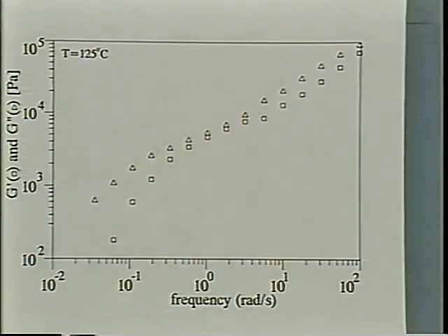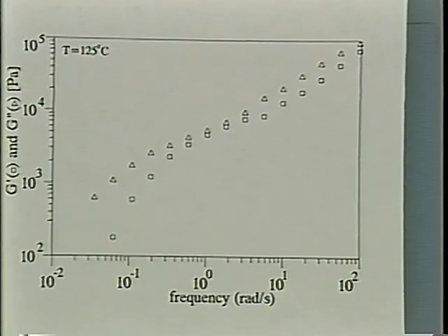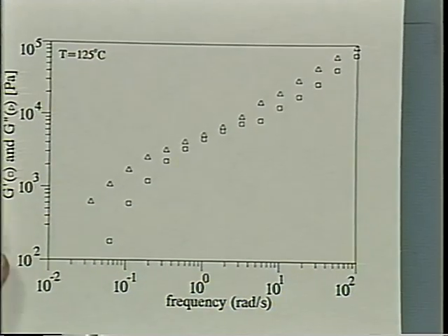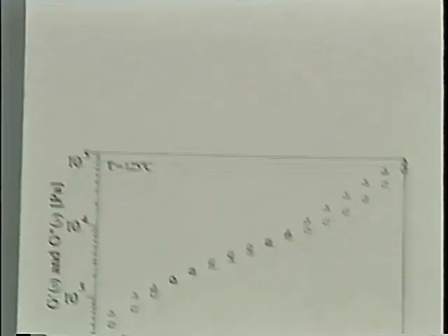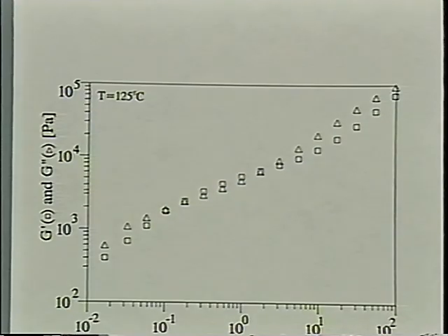And while the cylinders are healing, we are exposing the sample to large oscillatory shear. Just to show you how long it needs for the structure to build up, this is after 70 minutes. It's still a liquid here, G prime, G double prime going down. So it's a supercooled system, phase separated, as we know from Hashimoto's data, but not connected in a network yet.